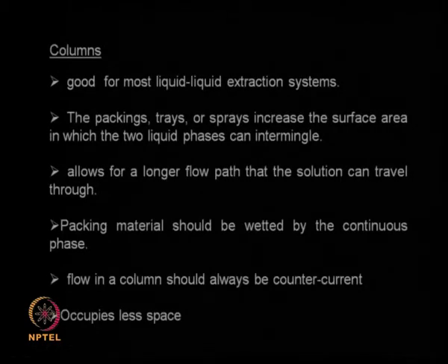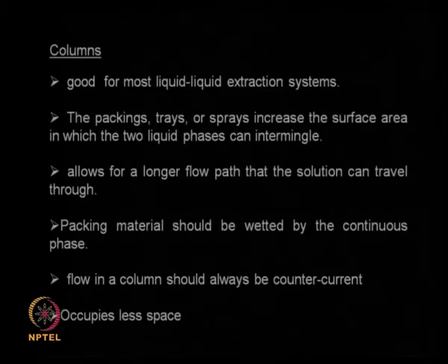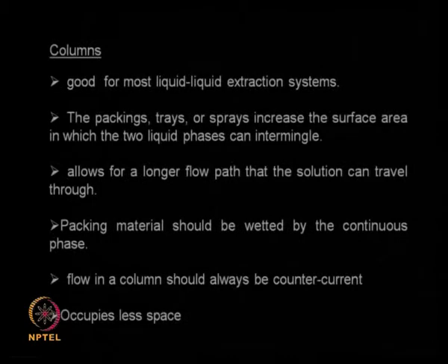Actually, columns are tall structures where you are bringing both your solvent and the heavies either in co-current or counter current fashion. They get mixed thoroughly because you will have trays or you will have packing inside the column. During those mixing stages inside the column, the partition of the solute takes place.